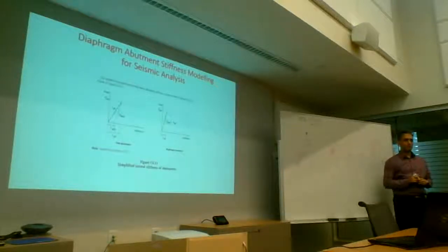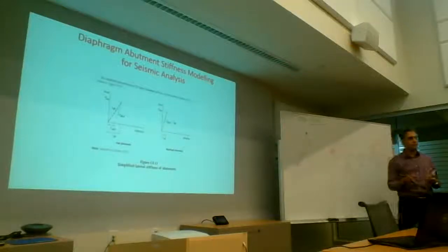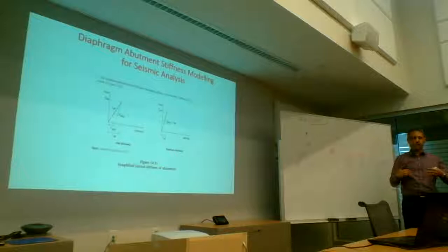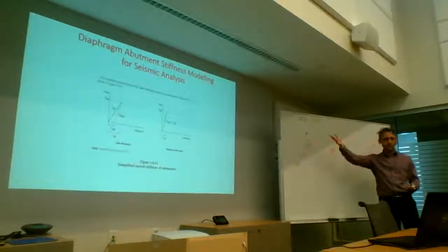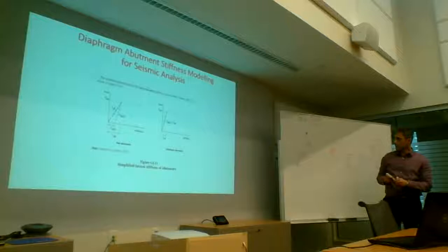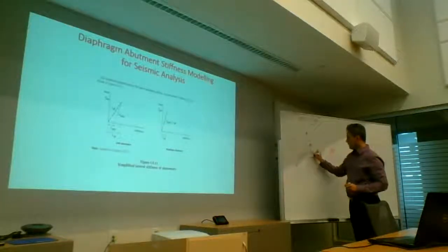I've converged. Usually, in my experience, 2 to 4 iterations are enough to converge, because in response spectrum analysis, there is no potential within the program to give you corrected stiffnesses. That only happens when you run pushovers by inputting proper nonlinear springs. You can't do that in a linear analysis. So now this is your appropriate stiffness because the load cannot go beyond that.